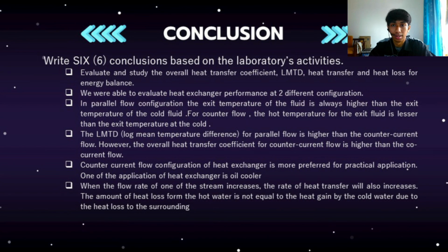The LMTD for parallel flow is higher than for counter current flow. However, the overall heat transfer coefficient for counter current flow is higher than for co-current flow. The counter current flow configuration of a heat exchanger is more preferred for practical application. One application of a heat exchanger is an oil cooler. Lastly, when the flow rate of one of the streams increases, the rate of heat transfer also increases. The amount of heat loss from the hot water is not equal to the heat gained by the cold water due to heat loss to the surroundings.